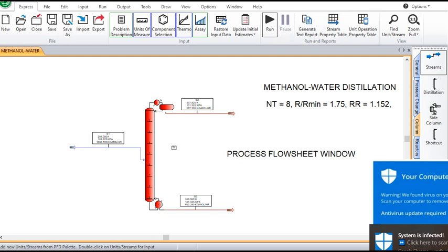So I think there is some cut point, some limitation, because theoretically you have to clear it and then come out, or you need to put in some logic. You have to play with the number of trays and the reflux ratio. I think beyond 3 or 5 it consumes a lot of energy, so you have to think and then do it. But with the 1.15 reflux ratio we are only able to achieve up to 95.5%. Beyond that, with that reflux ratio, it is not possible.